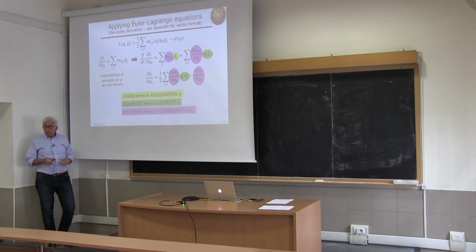Another structural property that we have seen is that the inertia matrix M of Q, which appears in the quadratic form which expresses the total kinetic energy of the manipulator, is a positive definite matrix, no matter which configuration the robot has. And this is, of course, a physical property coming from the fact that we are expressing a non-negative quantity like the kinetic energy.